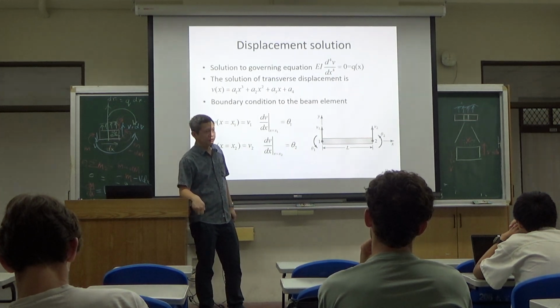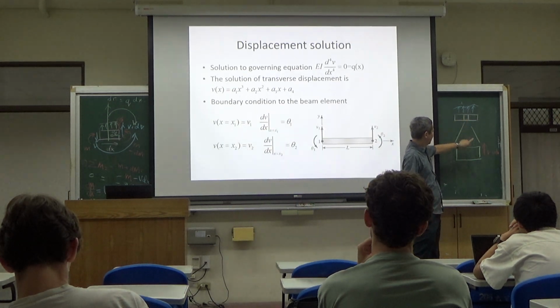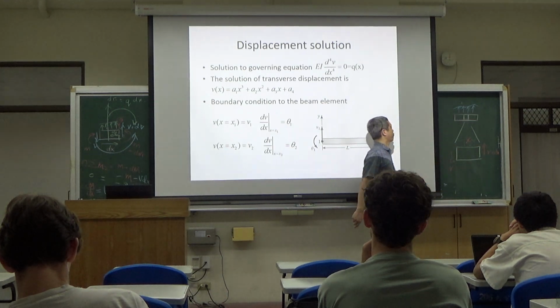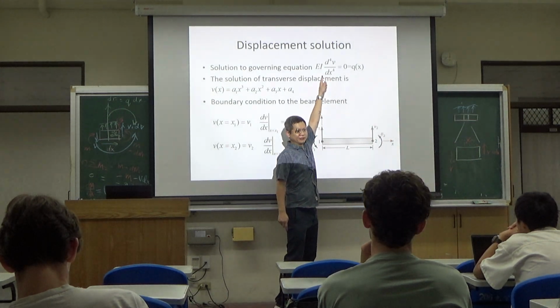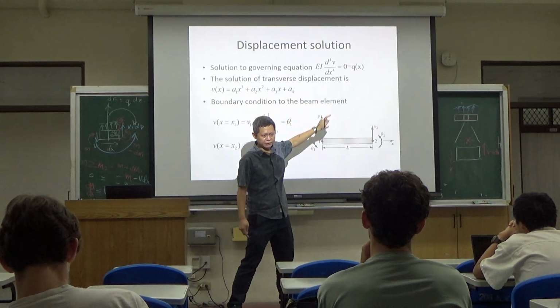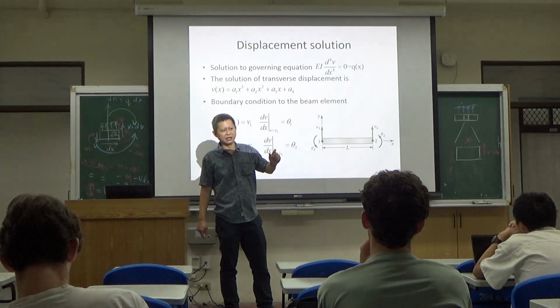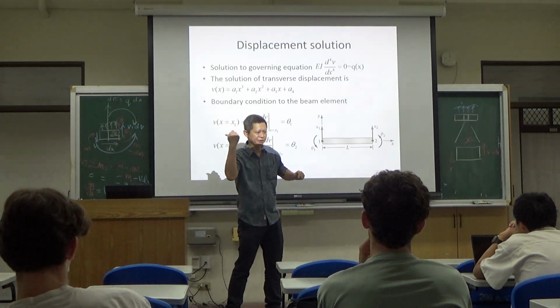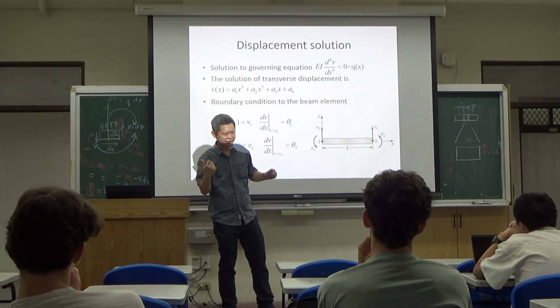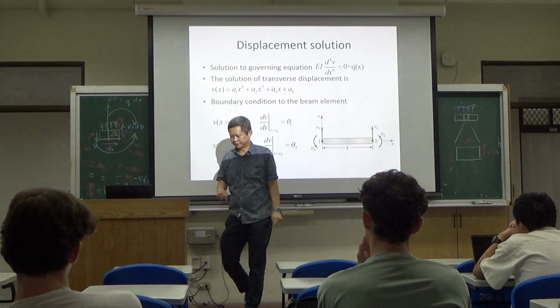You are only doing the finite elements by removing the distributed loading. So this is the first assumption we have, and you have to realize the consequence. If you take one beam element to do the modeling, you better go back to the mechanics of materials. That's more precise, because finite element has already removed the distributed loading.